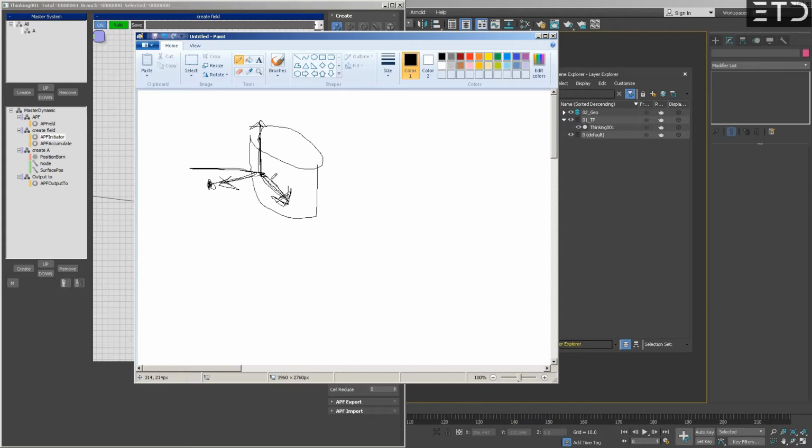And what we also do is blend between our original x direction, our incoming velocity, and based on distance to that cylinder, we blend into that resulting double cross vector tangent. So the closer the particle, or the closer the cell to the surface, the more it gets from that tangent. That way we get a smooth transition, and particles start avoiding the object before they even touch it.